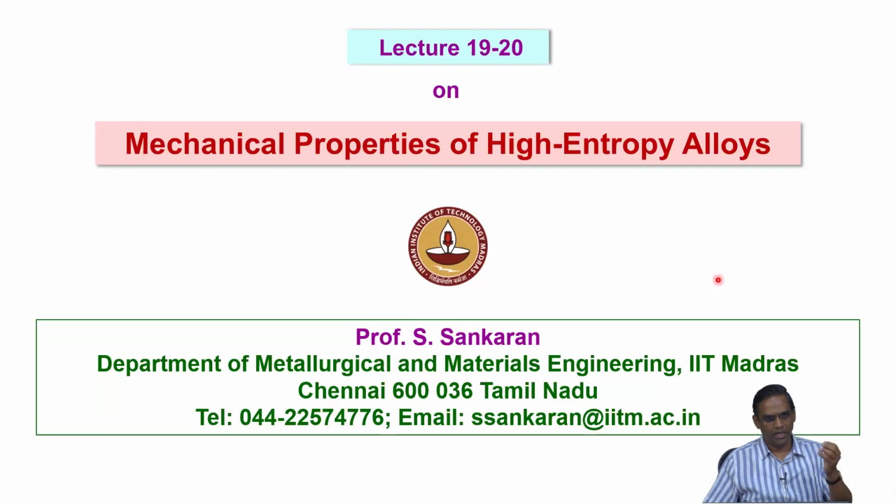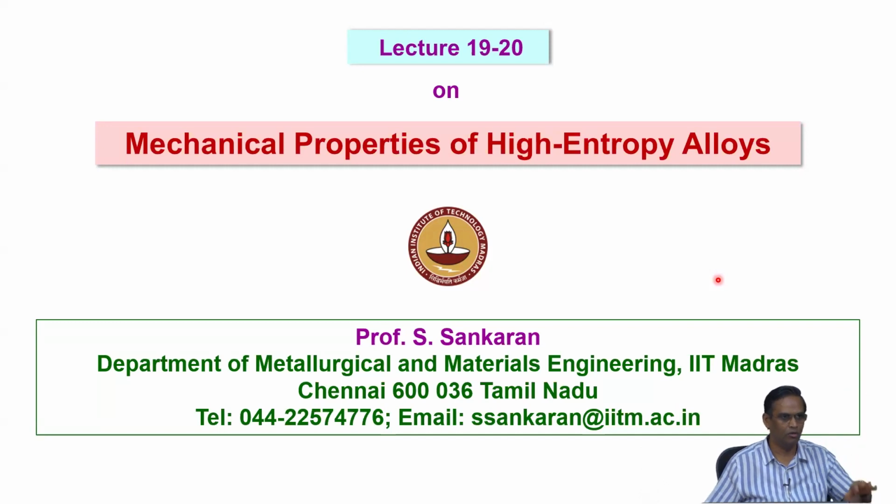So in the light of high-entropy alloys, in most of the high-entropy alloys, when you add additional multiple principal alloying elements, the stacking fault energy comes down.